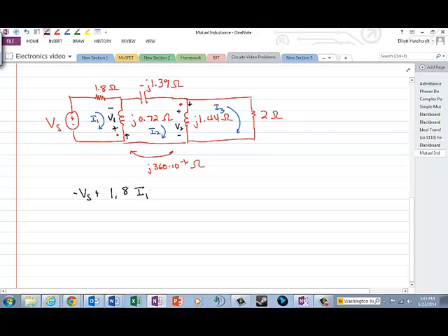And then remember, most of the time for the mesh current method we would want to have everything in terms of the current. So we'd like to do the inductance and all that in terms of mesh currents I1 and I2. It used to be that I would have just said j omega L times I1 minus I2 and go through it that way. But since we have the mutual term and we've got to make sure we incorporate everything properly, what I would do is just write the voltage and then we'll back substitute the voltage in. So I'll say minus V1, and that's equal to 0.